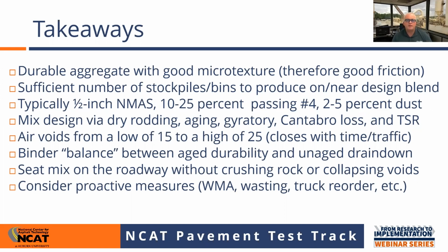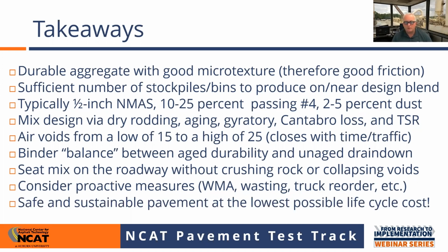Consider doing some of this proactive stuff. Some of it you can do in your specifications, and some of it is just practices that you can promote in the field. With warm mix asphalt you can reduce the temperature of the mix and reduce the absorption of the binder as a result of production through those reduced temperatures. You have higher effective binder contents. That's a good thing for mix health. You can waste mix, you can reorder your trucks, a lot of that stuff that I mentioned earlier. And if you do all this, our mission of safe and sustainable asphalt pavement at the lowest possible life cycle cost is attainable. We can do that.